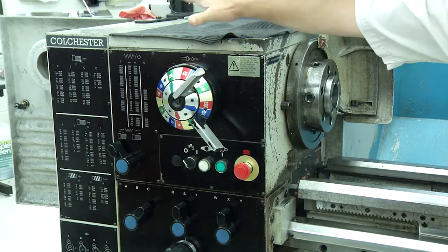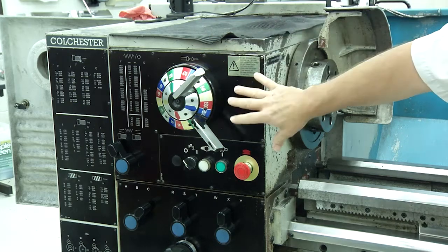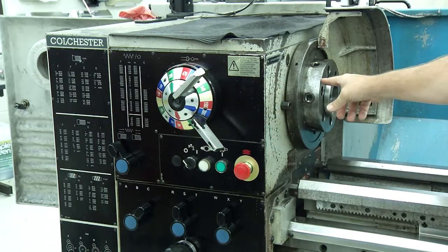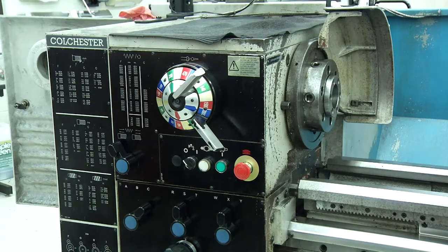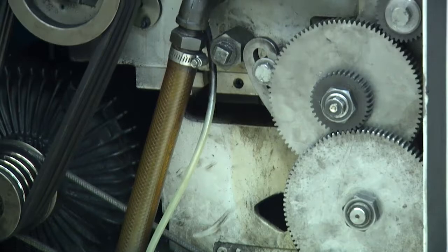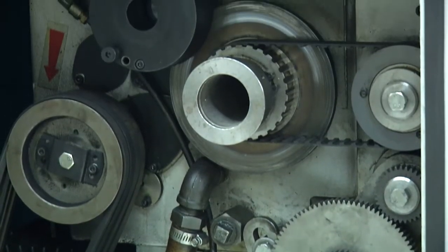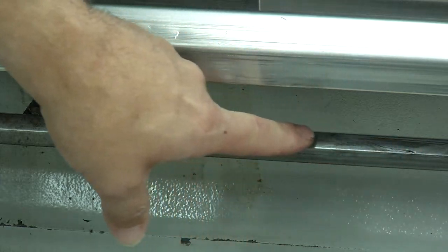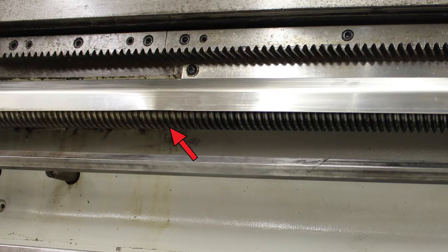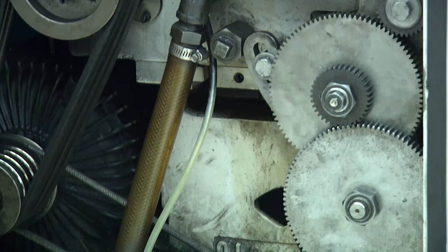The headstock houses the spindle and the components that drive the spindle and the feed gears. The spindle holds and drives the workpiece. The headstock also houses the change or end gears. Power from the headstock to the gearbox transmits through the end gear train to the feed rod and the lead screw. The size and positioning of the end gears creates a ratio that controls the feed rate.